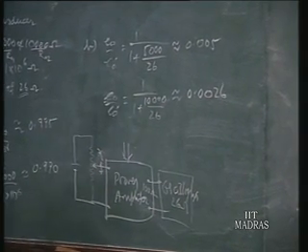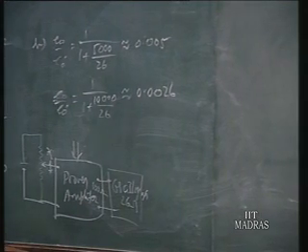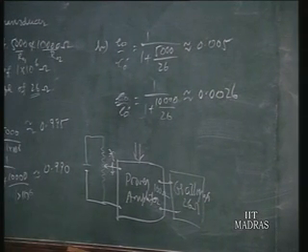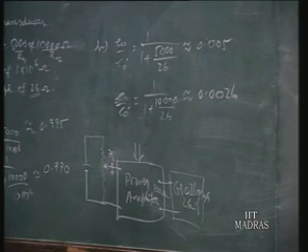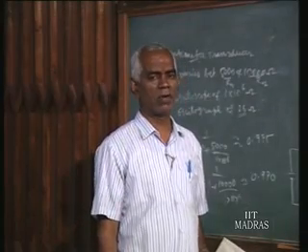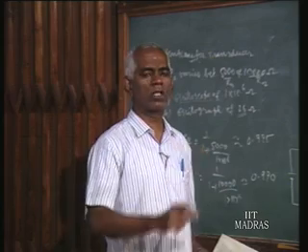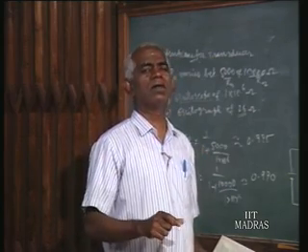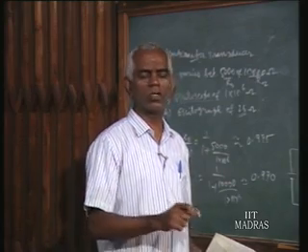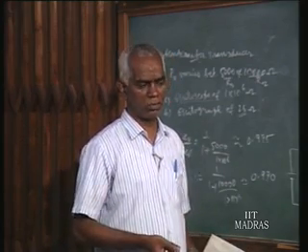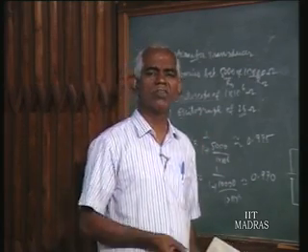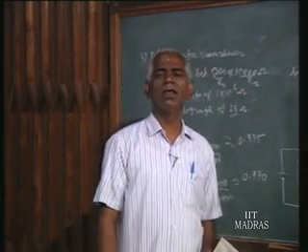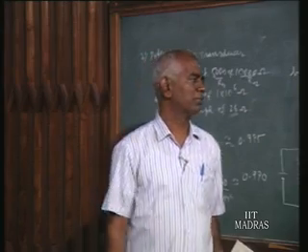Next we are going to see how to make use of the 4-quadrant diagram. We already learned the 4-quadrant diagram, where the different error sources within the instrument are identified by drawing the signal flow diagram, and we find the total effect of the error source on the input signal. From the total error we obtain a suitable least count, and that is what you are going to use when we manufacture the instrument. That is a design problem: how to decide the least count of a proposed instrument.